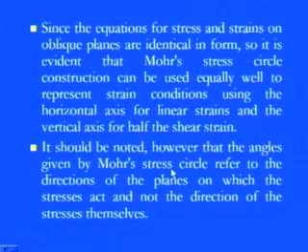Since these equations for the stress and strain on oblique planes are identical in form, as I told you, it is evident that the Mohr stress circle construction can equally well be used to represent the strain condition, using the horizontal axis for the linear strain. So here, to make the Mohr circle, we always take the x axis